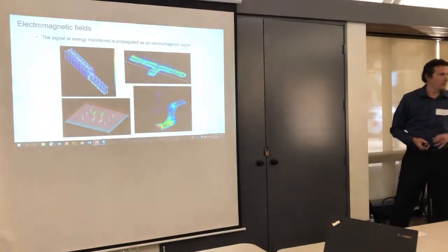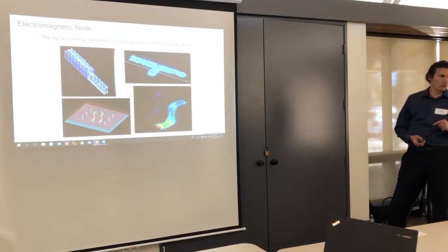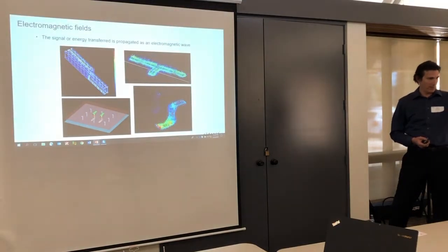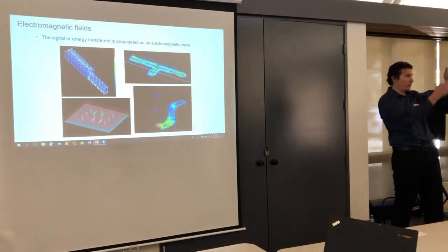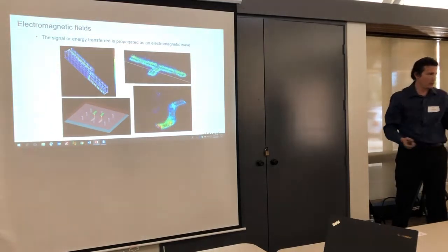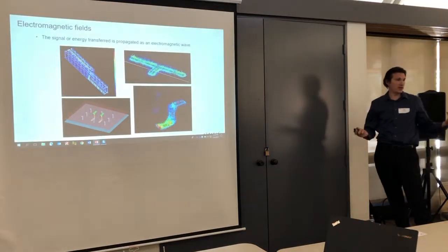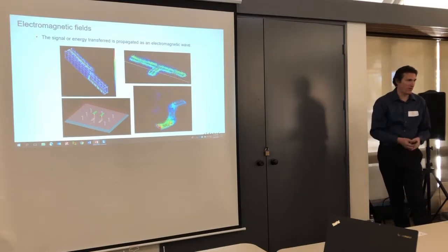Yeah, good question. You have a ground level until you route down from 1 to 3. Do you need a via? Only if you change your reference plane. It'd just be going to the other side, right? Right, yeah. And it also could depend on, if it's just going from layer 1 to 3, how big that stackup is, because there is going to be a period where it's on 1, referencing the ground plane, then it's going through, and then it has the dielectric, and then the signal layer, and then the ground plane below. So it may be something you have to run an analysis on, to find out what's the effect of having this return path via, what's the effect of not having it, maybe the effect of how fast the signal's going, right?